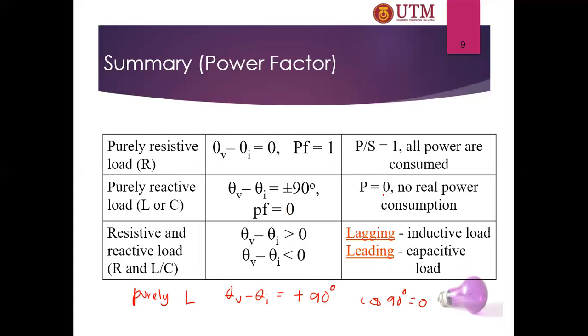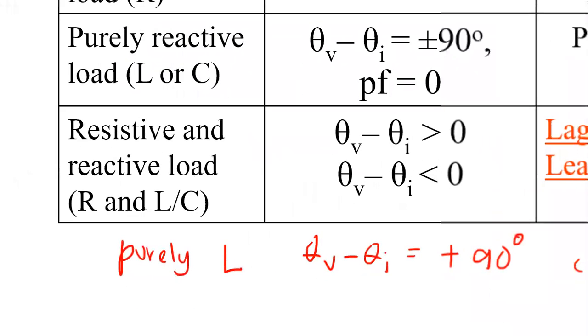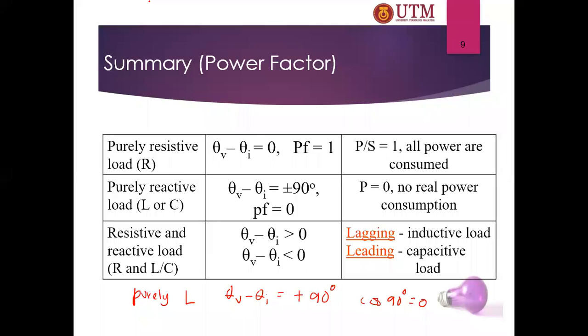So there is no real power consumed by the circuit. And if your circuit is purely capacitive, your angle theta v minus theta i is negative 90 degrees, and the power factor is also 0, and the average power consumed by this circuit is also 0.